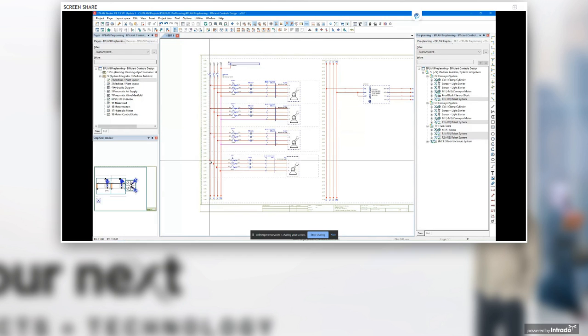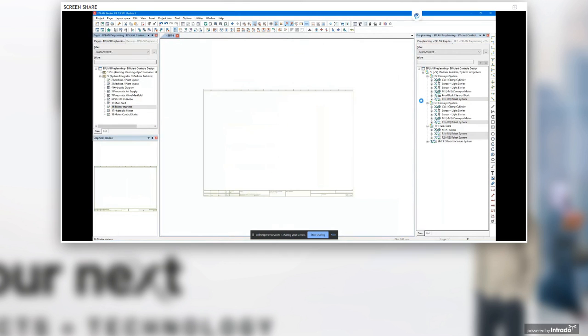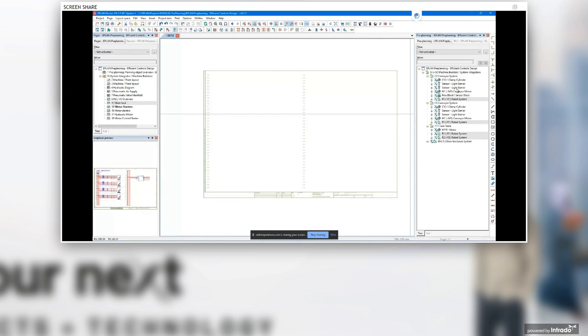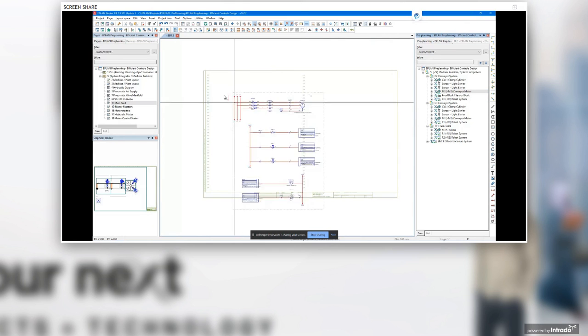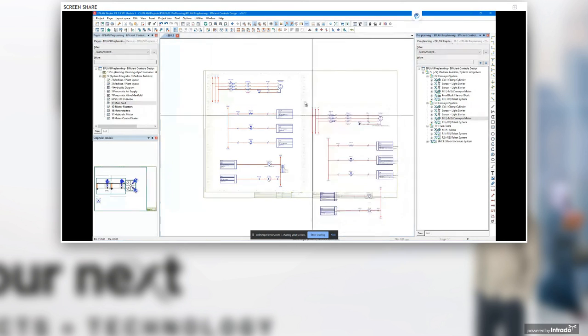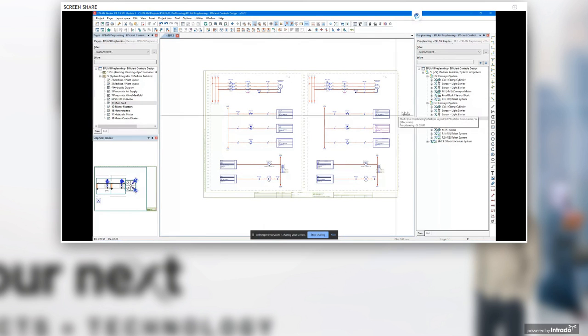So you can see that the information created through this overview helps you to leverage your design down the line pretty efficiently. Here are my motor starters. If I look at this particular motor starter, let's just switch over. I'm going to copy or create a new page here for my motor starters. Now I can take this motor here, just drag and drop, and now I've got my control circuit for that particular motor for my first conveyor, and here's that motor circuit for my second conveyor. It's as easy as drag and drop. So once you've got your objects, creating the schematics associated to the control system is pretty quick.